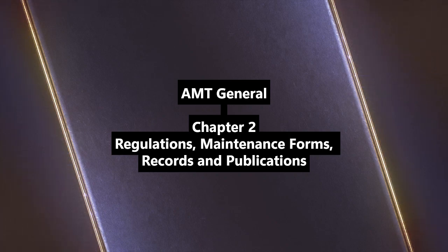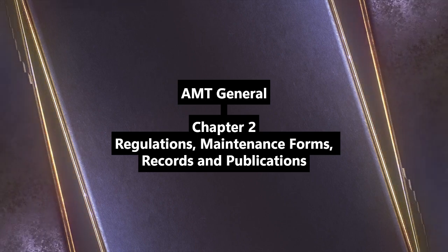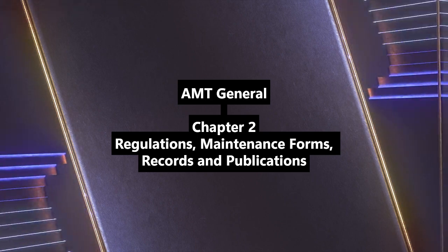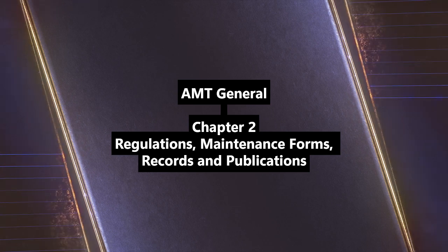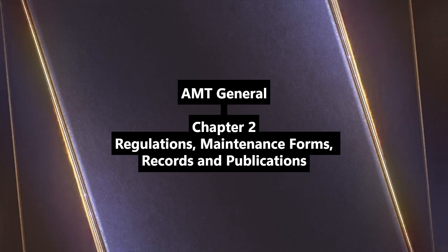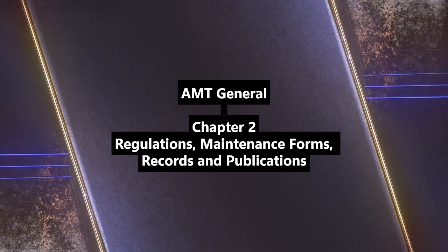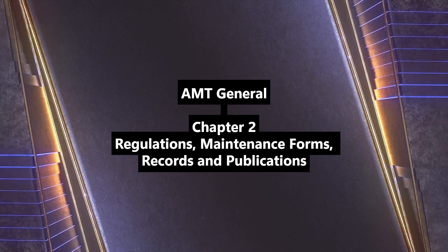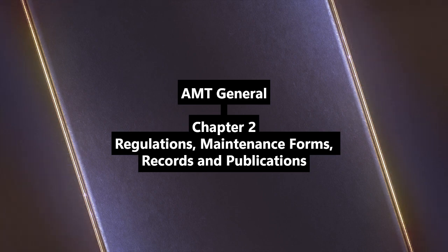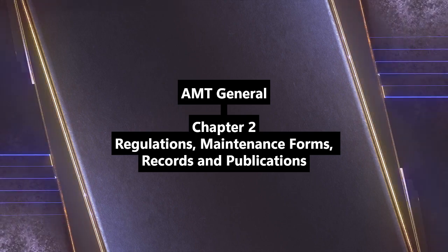Section 91.421, rebuilt engine records. The zero-time concept. Yes. If an engine is rebuilt by the manufacturer or an approved agency, it can get a new record showing no prior history. Must list rebuild date, ADs complied with, and manufacturer SBs incorporated during rebuild. Okay, that clarifies the owner-operator responsibilities under Part 91.